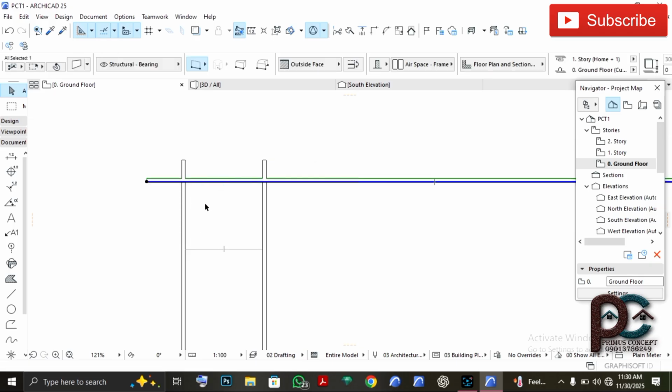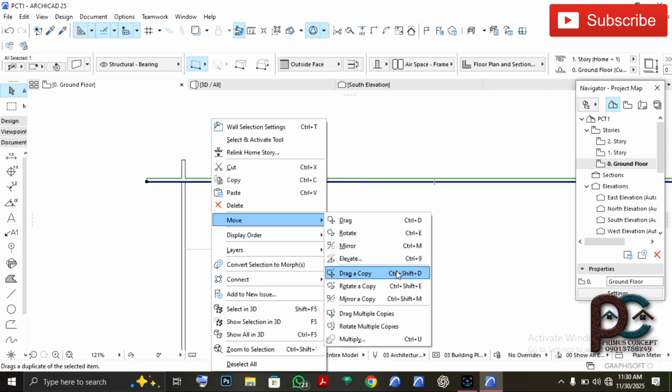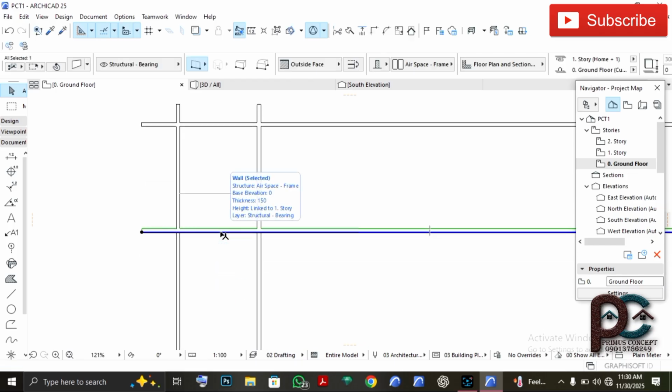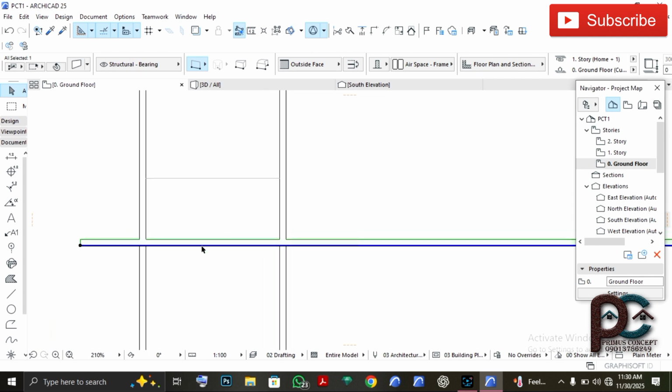And then I'll move this. And actually when I click, you will see the move, and you see drag a copy. Then you drag. I want to make it 4,200. So I'll use 4,350, adding the thickness of my wall, 150, and that's what we have there. And then I want to focus on this method. Let's not use 2 methods, let's use 1 method. That is it for now.